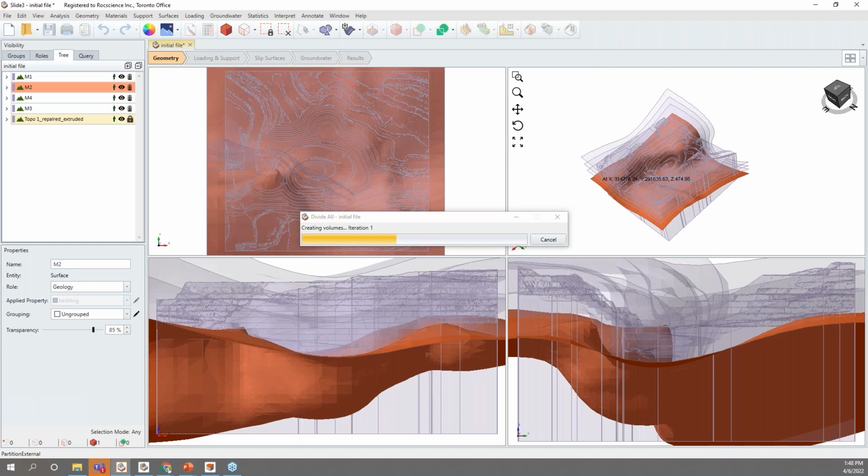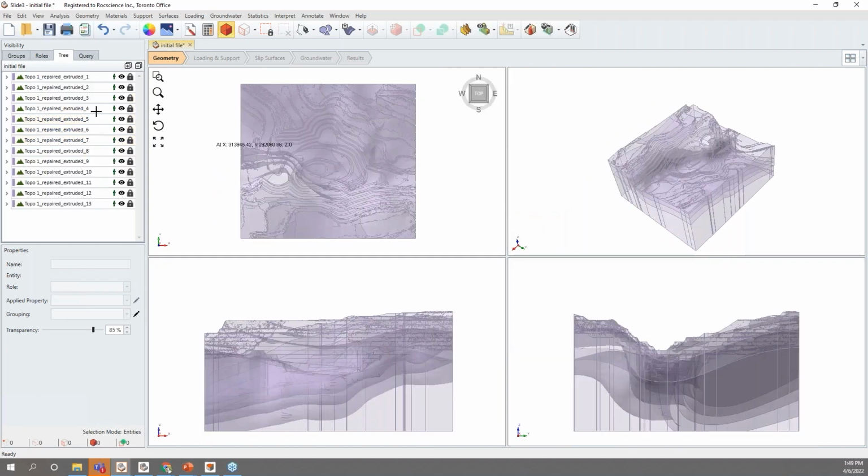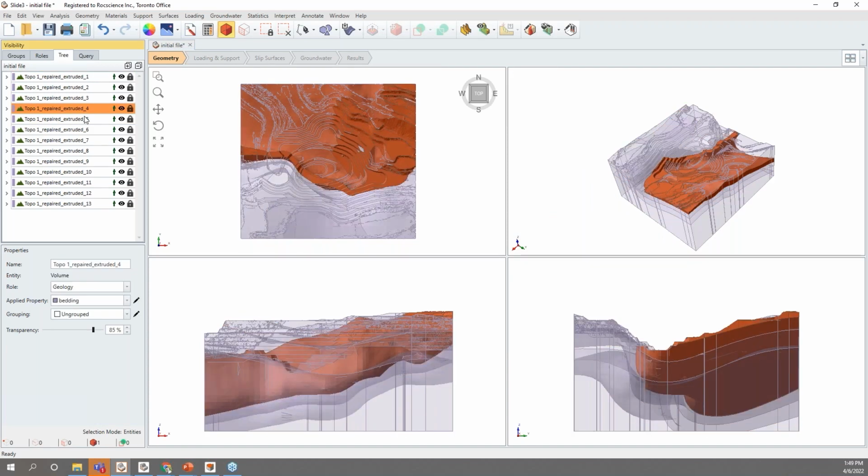Most of the time, you have small pieces coming up because these are mathematically intersections between surfaces and volumes, and you have a couple of surfaces at one intersection. So some small pieces may appear that can be part of a bigger piece. This is part of our geometry cleanup tool. It's actually in the repair tool. So you want a geometry that's clean, with as few entities as possible.